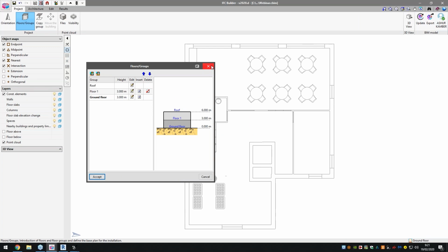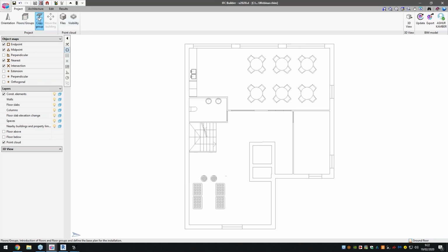Sifak asks, now it's a specific question. He asked whether we can make different heights in the same floor, like a part of the floor is 5 meters high and the other is 4 meters. What you need to do, just in short, is create 2 separate floors and define them as such as well, so the program understands that. But of course, I'll go into more detail about it a bit later if that doesn't answer your question. But moving on.